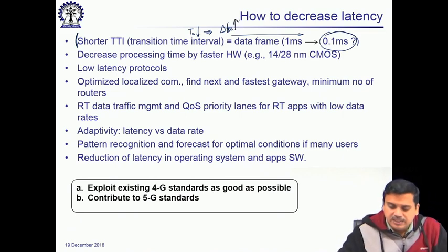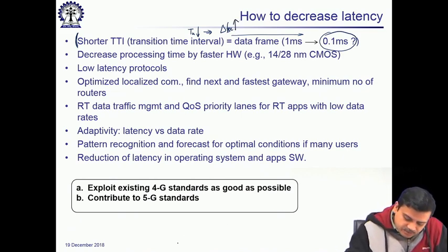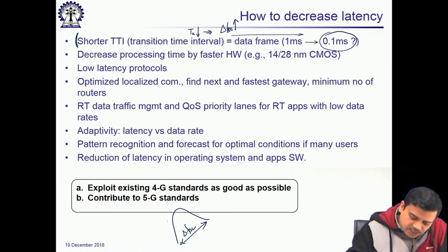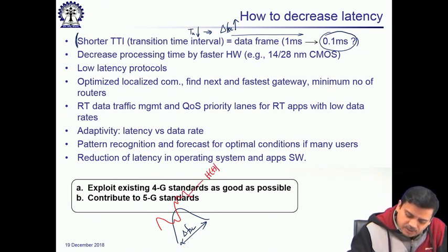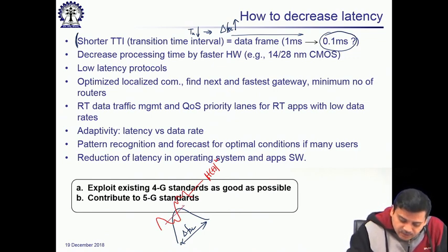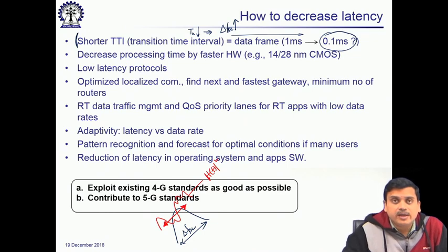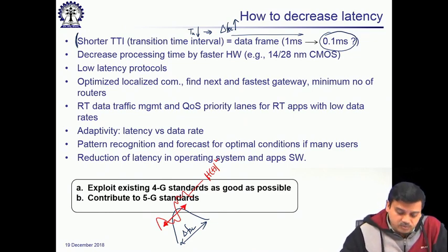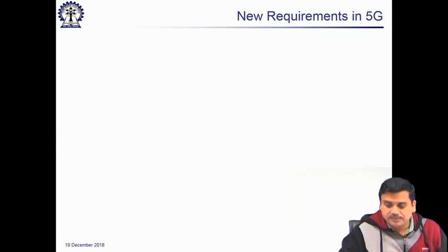If subcarrier spacing increases, then what happens is, suppose your subcarrier spacing is like this, it is some imaginary picture, this is delta f_SC, and the channel fluctuations are like this, this is the channel, mod of H(f) squared, let us say. Under this situation, addressing the frequency selective channel within the subcarrier spacing becomes a problem, because originally OFDM was designed to handle flat fading, and there was a single tap equalizer. Now if one has to get back and use a multi tap equalizer, then all the advantages of OFDM are gone. So, one would like to have some better mechanisms to address this.